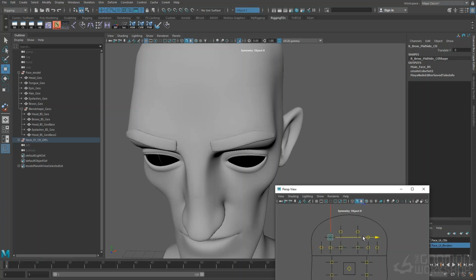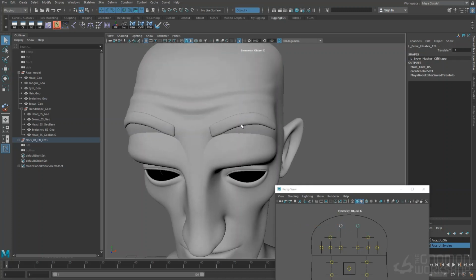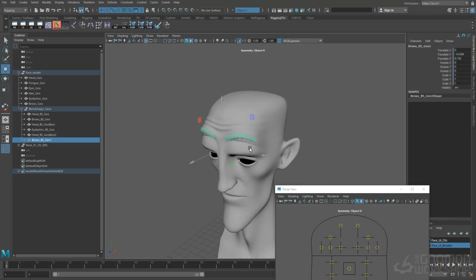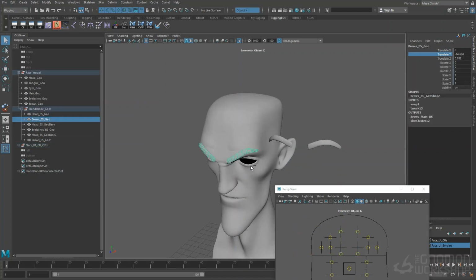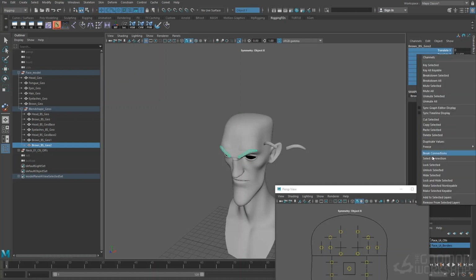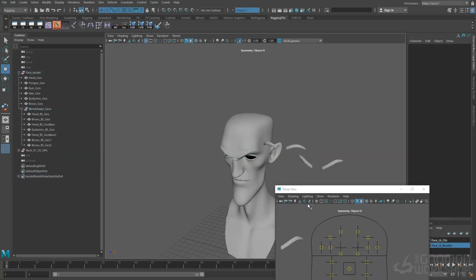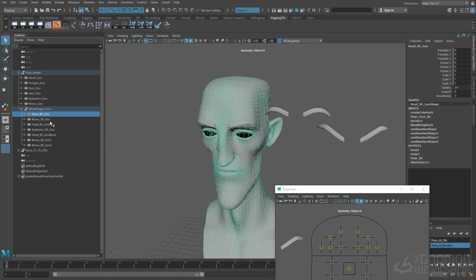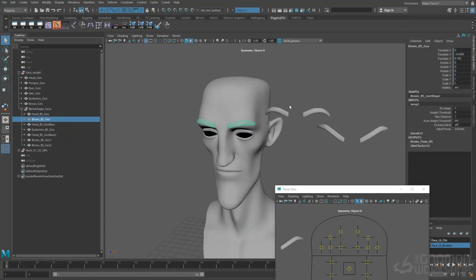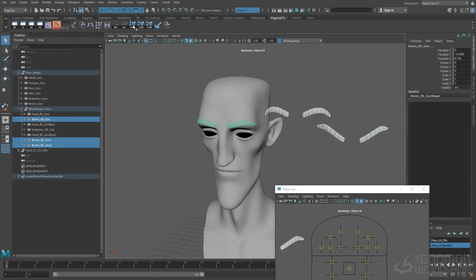Then you can duplicate this and start making your blend shapes for all of them, for all the brows. Then you can do the next one, that will be this one, and you duplicate, you move. So you can have duplicates for your brows for all the blend shapes in which they are involved. And once you have all the shapes duplicated, you can remove the wrap deformer on the brows, so this one, with delete by type history, and now you can do blend shapes to the brows.